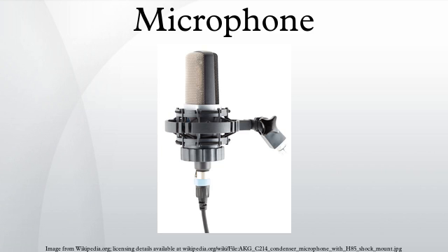Recently some microphones with low noise specifications have been introduced in the studio entertainment market, such as models from Neumann and Røde that advertise noise levels between 5 and 7 dB. Typically this is achieved by altering the frequency response of the capsule and electronics to result in lower noise within the A weighting curve, while broadband noise may be increased.